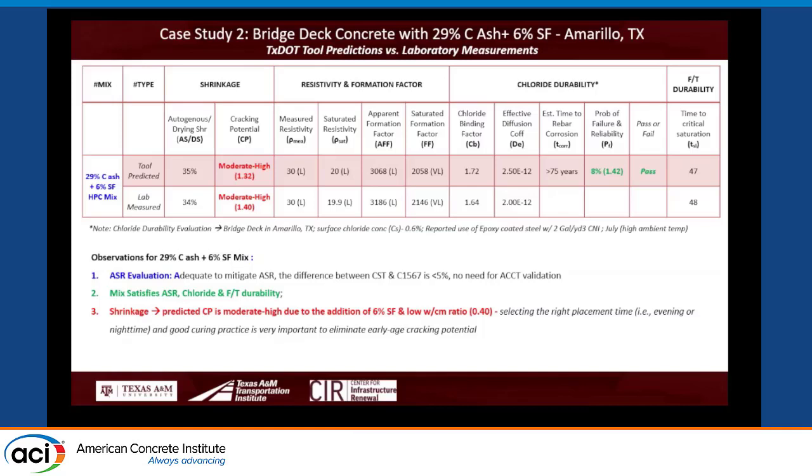See, you are considering all the 4 durability aspects at the same time. Sometimes people focus on ASR. What about the other 3? Sometimes chloride is too much. What about ASR? All 4 need to come together. This is a good example. So basically what we are recommending, this mix still works, but make sure that your time of placement is selected properly. You don't introduce any extra thermal strain. It should be okay.